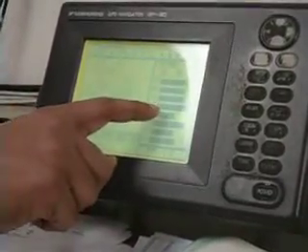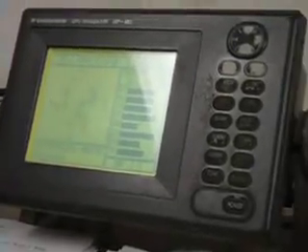Now this bar is the signal to noise ratio. Same like our mobile telephone. 3 bars very good, 1 bar very little. So the longer the bar length, the signal is good. The shorter the bar length, the signal is bad. So by looking here, satellite number 17 and 23 have very good signal, but satellite number 20 bar is less, so signal is weak. Understand? Yes, sir. Describe satellite in view window. So this is the in view window. The ones which are circled, we are getting signal. The ones which are not circled, we are not getting signal.